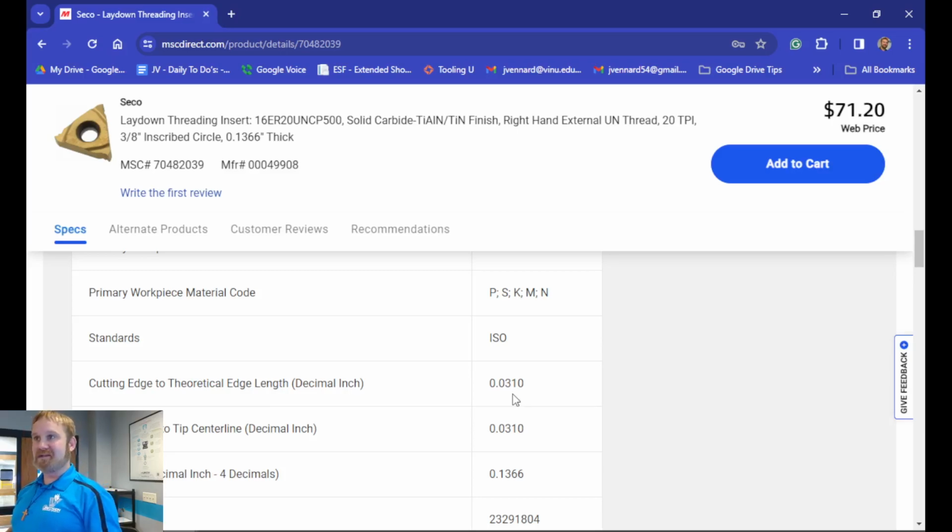And that's why we were getting such a nasty cut. It was cutting because it's carbide and aluminum, but the bottom side doesn't have all the cutting geometry correct to give us a good cut. And we couldn't fit, like we fought it. That was like 2 years ago or so, but I remember him coming, he's like, I've adjusted this like 25 thousandths and it still doesn't want to screw together. It's probably why it's broke now. He probably overcut the threads too deep.